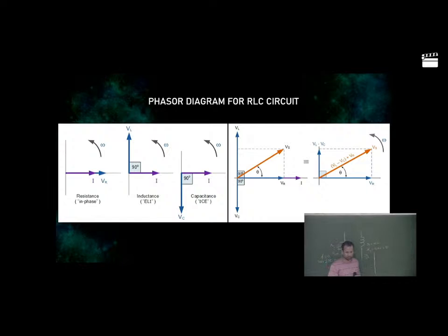Okay. Now, two more things. Inductor does not allow sudden change of current and capacitor does not allow sudden change of voltage. So we are trying to analyze why it is happening, right? We know the expression IC = C dVc/dt, right?